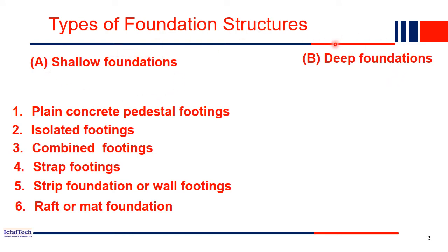But if the soil quality is very poor, if you have so much sediments on the soil surface, like in the Gangetic basin in North India, there you will find the soil quality is a little bit poor. In that case, shallow foundation may not be the ideal option. If you want to construct a multi-story building, then you have to go with deep foundation. Okay, so up to the bedrock level, you have to take care. I mean, you have to extend the foundation. So these are the different types of foundation.